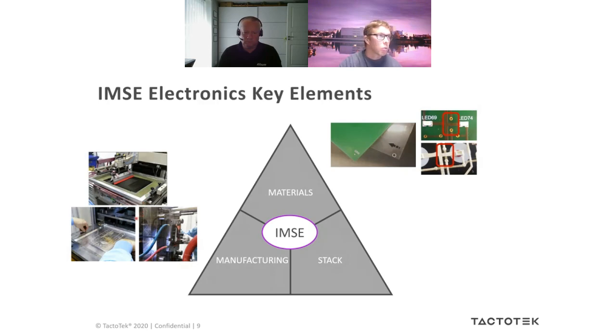The 3D form of our electrical circuit is obtained by thermoforming, and we do the injection molding for creating the mechanical structure of the product, and at the same time we are encapsulating electronics within the plastic. Because we have different manufacturing methods, our design for manufacturing rules are different as well.